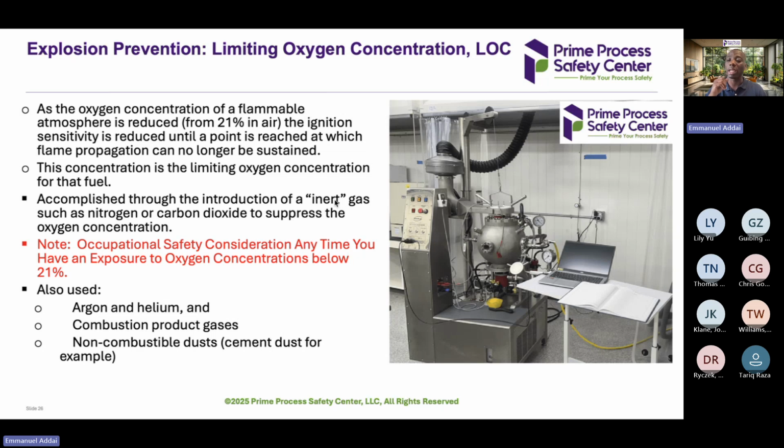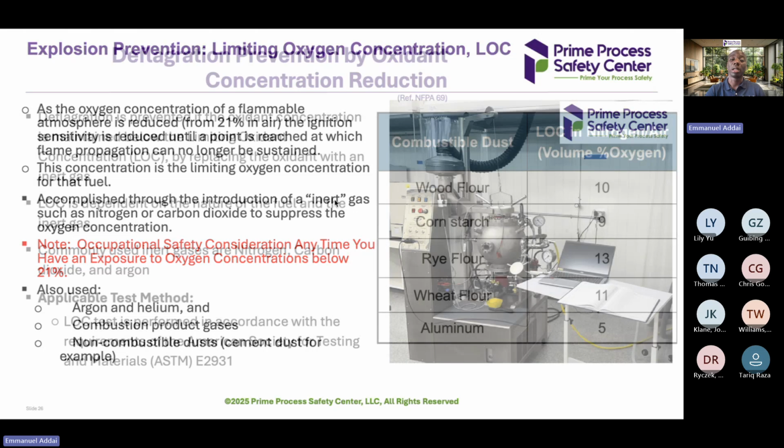Last year, we did a project for a client who has a 3D printing system, and the 3D printer continues getting fire upon fire, sometimes a big flash fire. They called us, and I spoke to the client and I explained what is going on. He said, yeah, we are inerting the system with argon and still we are getting fire. Then I said, okay, first of all, do you know your limiting oxygen concentration? They said no. Okay, can you take samples to the lab for us to test? They brought a sample. We tested it and the limiting oxygen concentration was 3.5. Then I called the client back. Okay, so how do you set your system for the argon? What is the oxygen level? They said it is 6. That means even though they have a good intention of using avoidance of oxygen as the basis of safety, they are doing it the wrong way because they don't know the limiting oxygen concentration. That is very, very important when it comes to prevention of any kind of dust explosion.